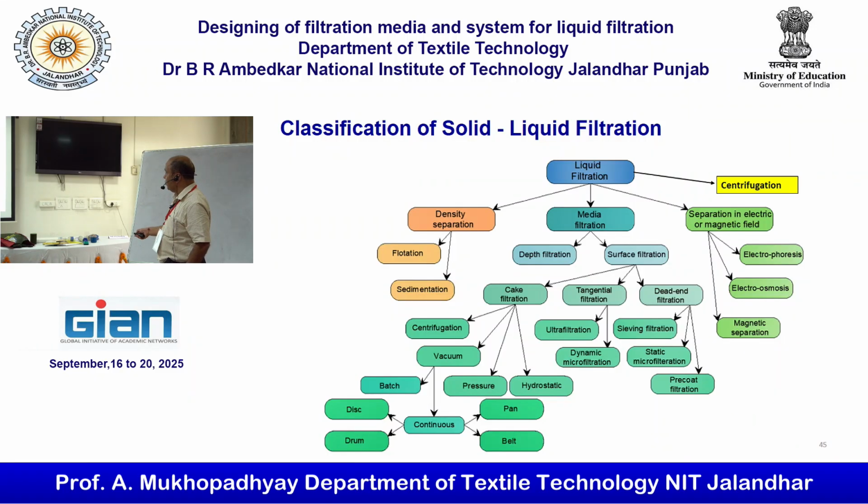The center one is where we are using filtration, and there the role of filter media is very important. Here we can have the media where depth filtration is important, and surface filtration. Surface filtration can be further categorized as cake filtration, tangential filtration, dead end filtration, and so forth.